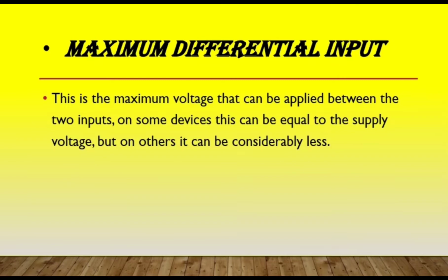This will not always show up in the simplified schematics of the amplifiers. It will show up, however, as a differential input voltage specification of plus and minus 700 millivolts maximum.